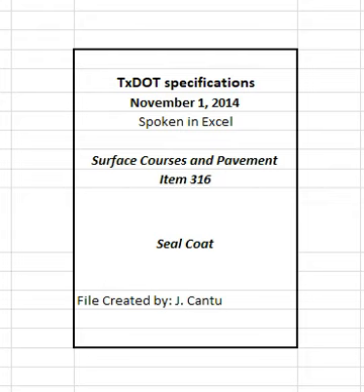5.2 Aggregate. Aggregate will be measured by the cubic yard in the trucks as applied on the road. Strike off the loaded aggregate for accurate measurement when directed. 5.3 Loading, hauling, and distributing aggregate. When the department furnishes the aggregate, the loading, hauling, and distributing will be measured by the cubic yard in the trucks as applied on the road.